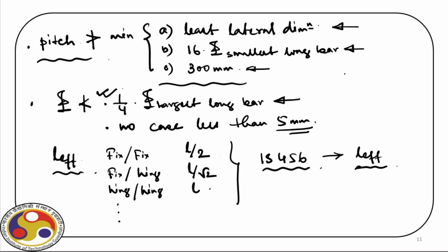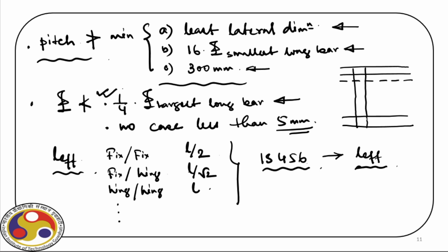So if we have a slab here and then a floor here, and just imagine there is a beam for this slab, and we have a column, then first we find out from the soffit of the beam the clear height of the column, and then based on the boundary conditions here and there, we decide the effective length of the column.